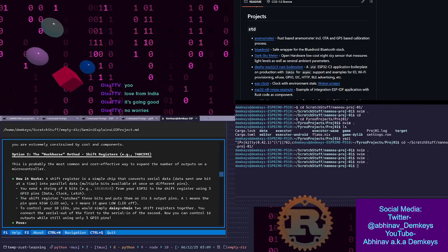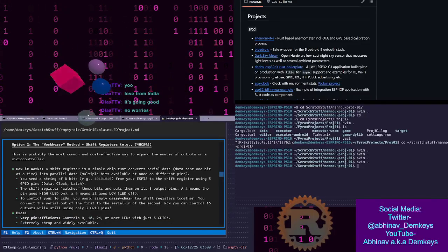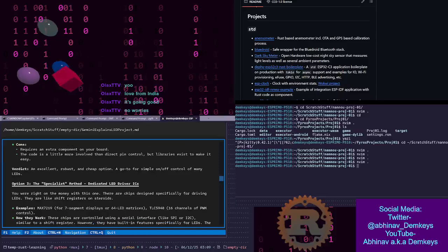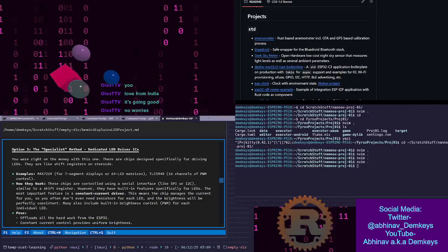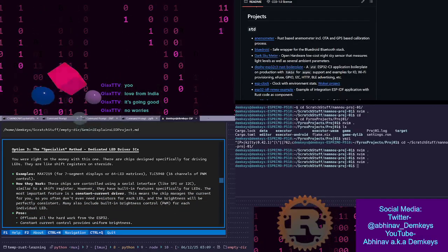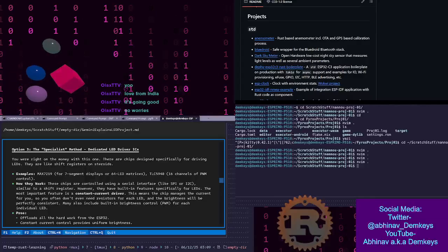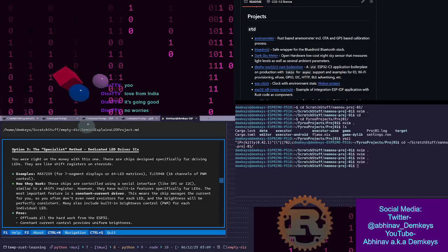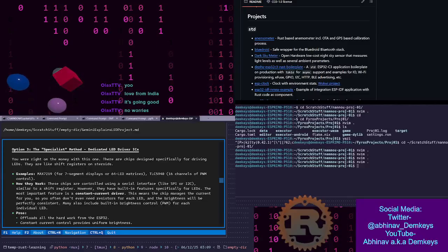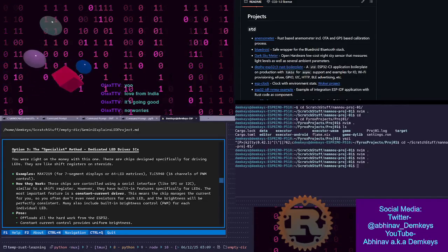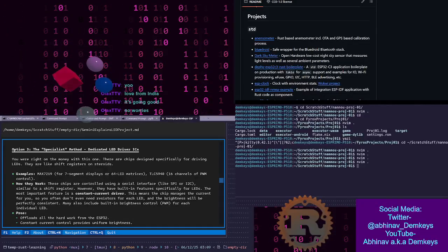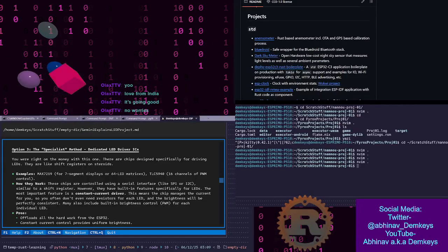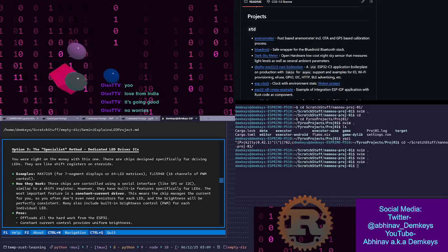Another method was to use an LED controller module like this one, dedicated LED driver ICs. I'm assuming even the power for these ICs would be external. You would probably have to power the module separately, like DC and servo driver modules, where you have to give them power separately. You can't just pull power from the ESP32. But that's an option as well.